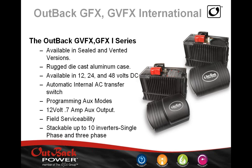But the important thing to note is that if we wanted to use a grid interactive inverter in an off-grid situation, it would work. Where we would run into an issue is if someone had a low-quality generator that didn't have the voltage or frequency regulation that these inverters look for, or if it had poor power quality in terms of harmonic distortion and power factor.